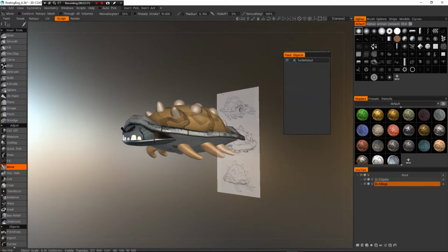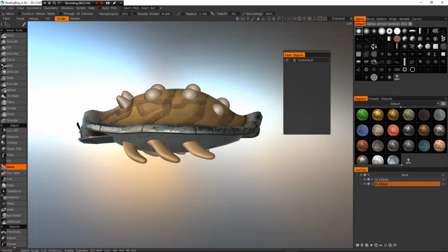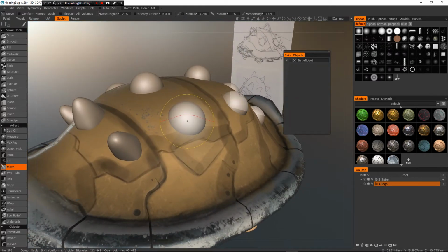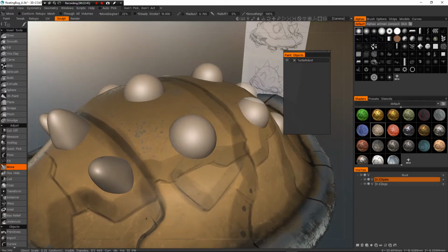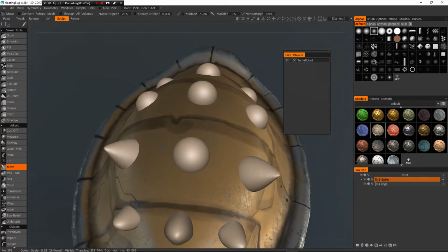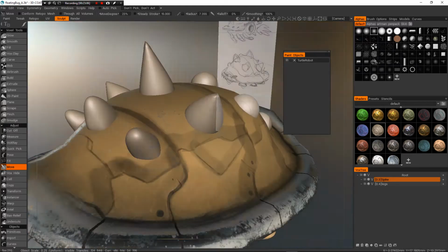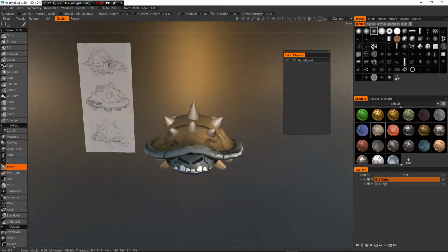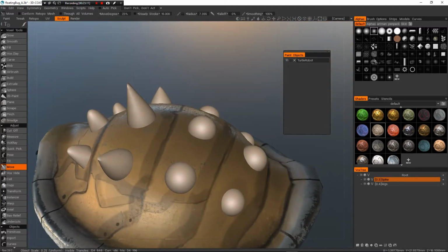Okay, so now with that, I'm gonna start turning this into geometry. Let me fix these guys, the shape of these. So I'm just gonna hover over it and press H, and you'll notice over here, my layer will switch to this layer. So basically that's just a quick selection. I'm gonna go into my move brush. I will choose a brush with a pointy alpha. I can hold down Control while clicking on something to basically move out on the surface normal. So it's going to move it directly outwards from that position. That's probably too pointy. That's okay, I'll fix it after.